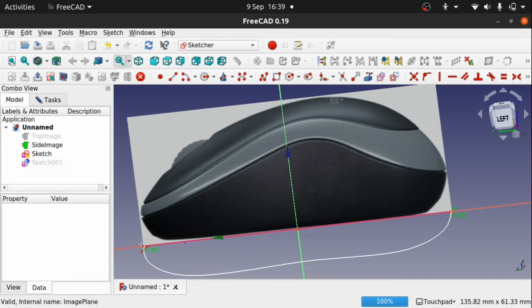We're going to be creating lines that are constrained against here and making sure they're vertical, like so. And we're going to be connecting up to these lines using the Create a B-spline in the sketch. Now we're going to start beyond. There's a reason for this, so we're going to start here, and we're going to connect up to that line with a point on object constraint, and we're going to follow through with sketching all the way around.